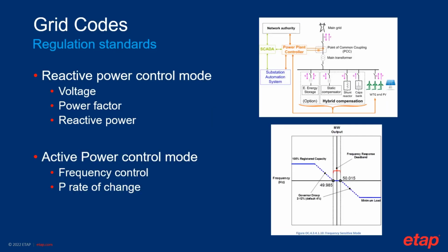Nowadays, highly demanding power control functions are requested by the system operators. Currently, to meet the most challenging grid codes, large renewable power plants must include a power plant controller. It should be capable of managing both active and reactive power with fast response time for different control modes.